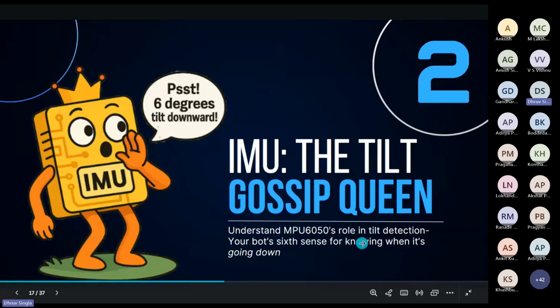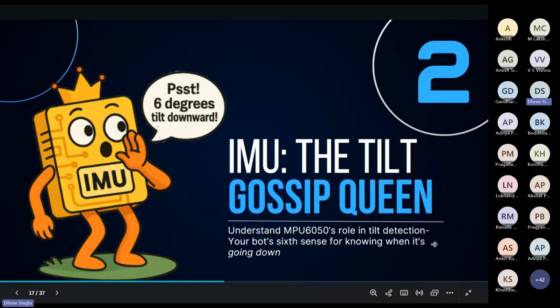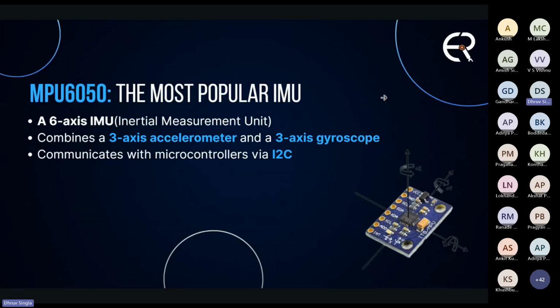So what does it do? Let us understand the working of it and how it works with the board to give the data regarding the angular coordinates of the system. So what basically is an IMU? IMUs are devices that help us derive the current physical quantities of the system, like its speed, angular velocity, or the magnetic fields around it. So it can have 3 types of devices: accelerometer, gyroscope, and magnetometer.